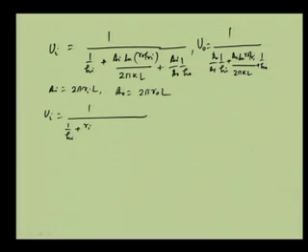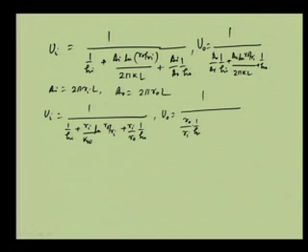Fine. So, in that case we can finally write that Ui is equal to 1 by [1/Hi plus Ri/Kw into ln(Ro/Ri) plus Ri/Ro into 1/Ho]. Similarly Uo can be written as 1 by [Ro/Ri into 1/Hi plus Ro/K into ln(Ro/Ri) plus 1/Ho], where K is the thermal conductivity of the wall material of the tubes.